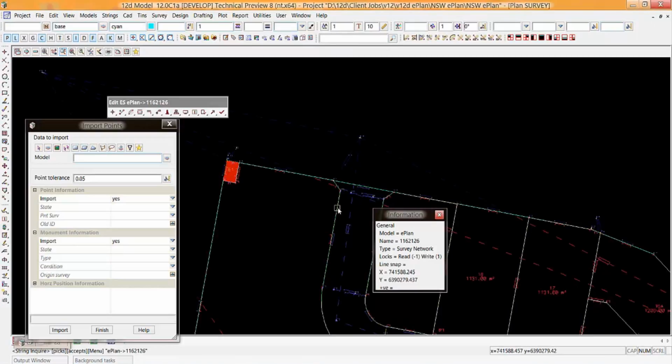Now this is a new feature just for ePlan, and it's also similar to the least squares stuff. It's essentially a points based system or model inside 12D, and you know 12D model is string based, so it's a unique feature, and they've made this points based because, as you know, when you have a point and you have a lot with 4 segments going into it, you can have 4 points there at that corner.